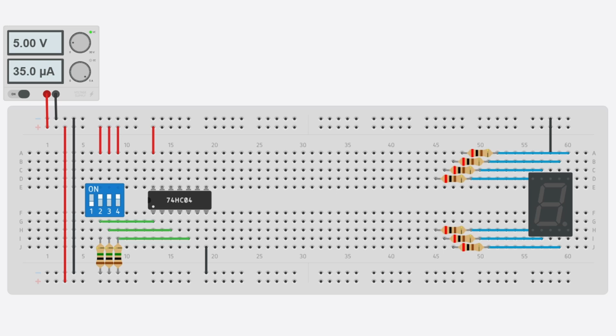And as we said before, we'll connect our inputs directly to each of our 3 input pins on the IC as shown. We can see that even with all 3 of our input switches closed, the total current is still only 35 microamps.